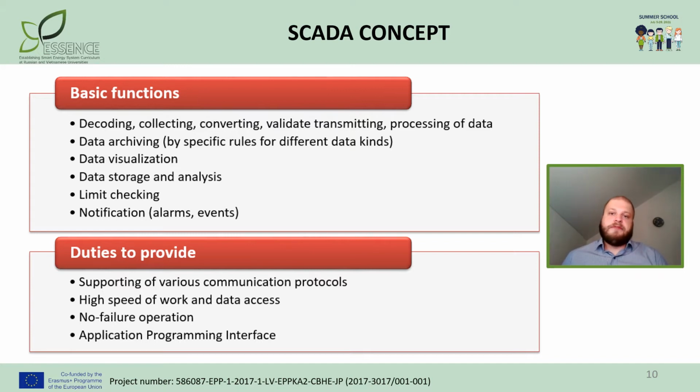The next important feature is data communication. In real life, you want to be able to monitor multiple systems from a central location, like a central dispatch control center, monitoring the state and operation mode of all the power system facilities within the control zone. That means you need communication networks to transport all the data collected from your sensors.